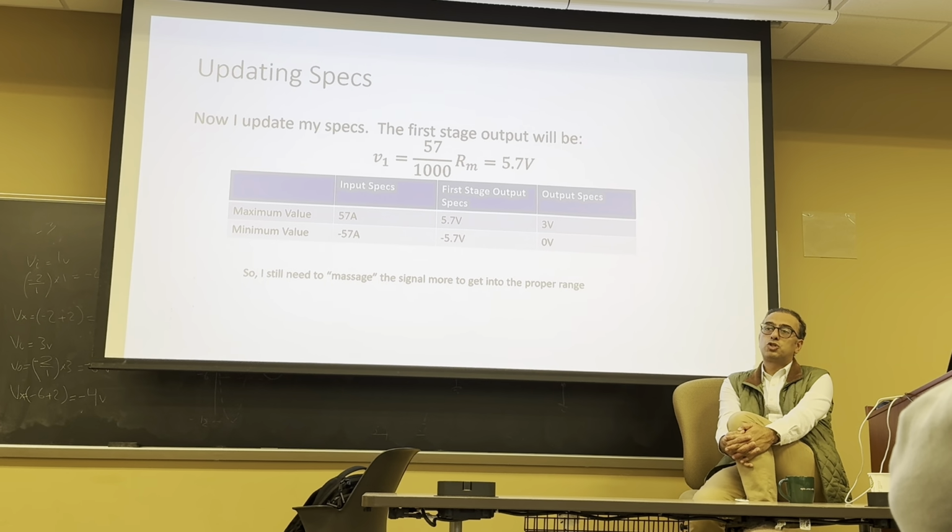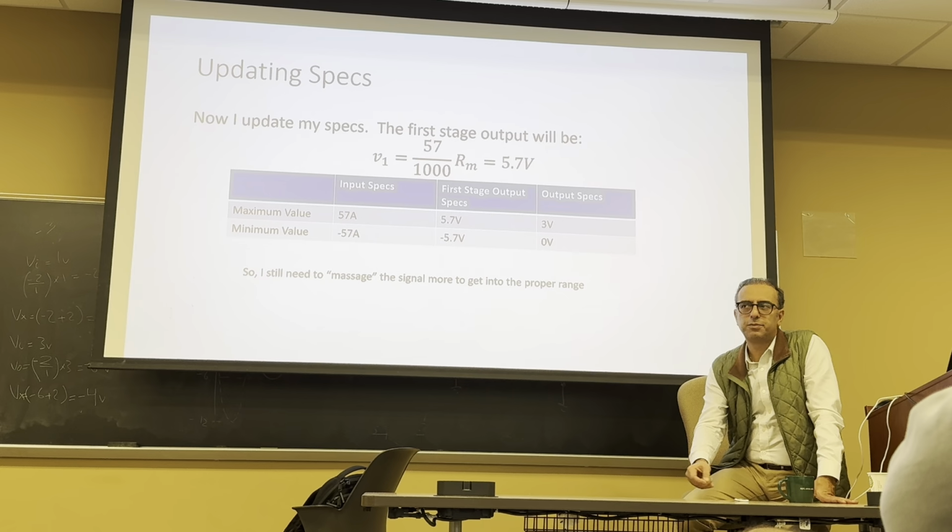So in other words, the choice of sensor and sensing technology that you are responsible to acquire determines what value and what conditioning circuits you're using. For instance, when you're dealing with a 50 amp application, you cannot just choose a 50 amp sensor.